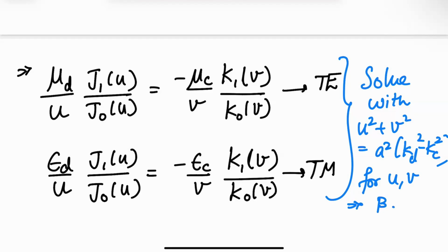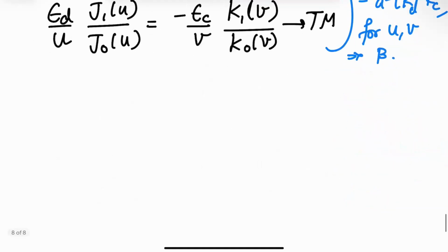Okay. So keep in mind that the TE and TM mode solutions for a fiber optic cable have no azimuthal variation. If they have no azimuthal variation, that is actually a nice intuitive picture as to what's going on. So these rays are called meridional rays.